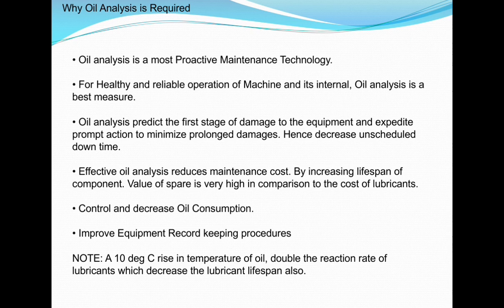Oil analysis predicts the earliest damage of the equipment, and by doing it we can know whether there is metal wear out or a chance of wear damage in the future, and accordingly we can take proactive action.